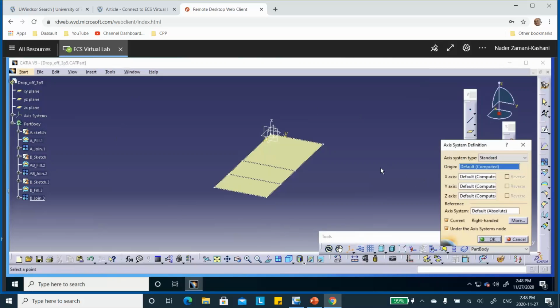Since I'm not plotting, since I'm not getting the contours of stresses in different plies, all I need is a single Rosette aligned with the global coordinate system, because I have no intention of doing a ply by ply stress plot, at least, yeah, stress plot along the normal and transverse direction.